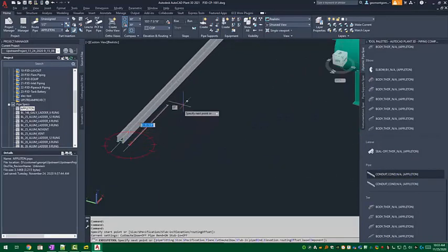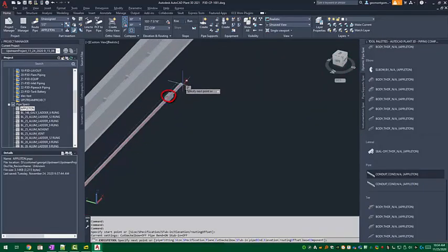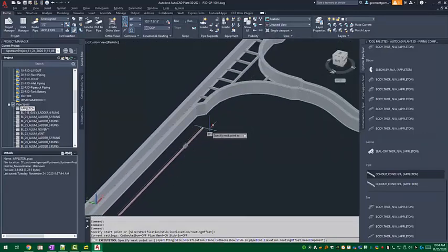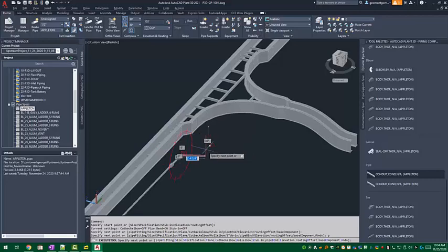One thing that you'll notice is that Plant 3D automatically adds in couplings between each conduit length. This is a feature that we enabled for use with ELECTROWorx in the Plant 3D Project Manager. Instructions on how to add these automatic couplings are included in the ELECTROWorx installer. I'm going to route conduit just slightly below this T so that I can continue this run. So I'll choose a 30-degree bend here to complete my path.